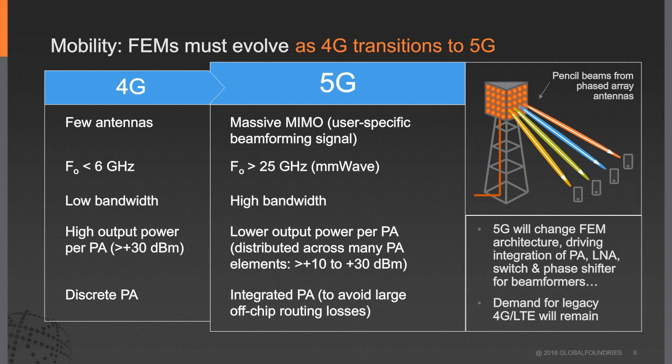However, there are some drawbacks in which there's not enough robustness for mobile broadband applications due to increased propagation loss at millimeter wave frequencies and susceptibility to blockages. So it's like building penetration. All of those are some of the issues that millimeter wave 5G faces. However, advanced antenna techniques that are being introduced with 5G new radio or 5G NR, the global standard for 5G, are changing this.